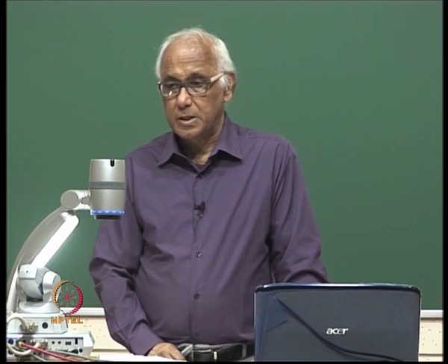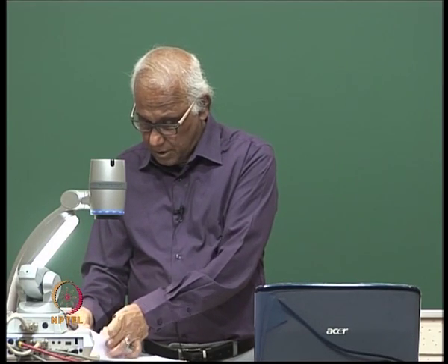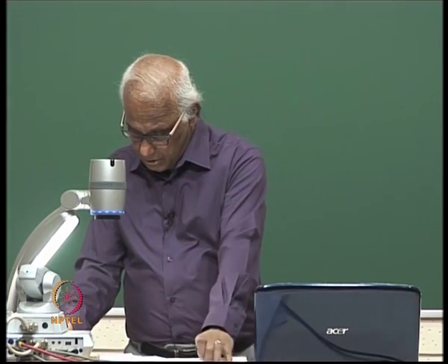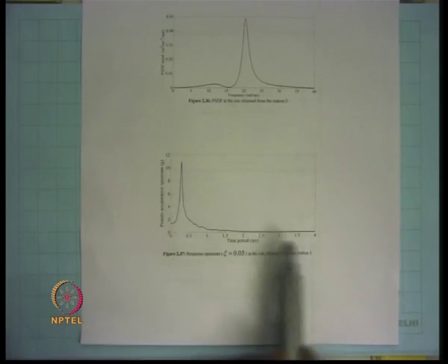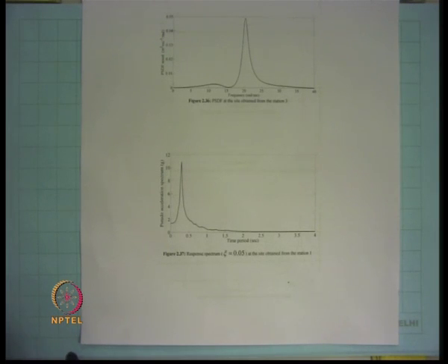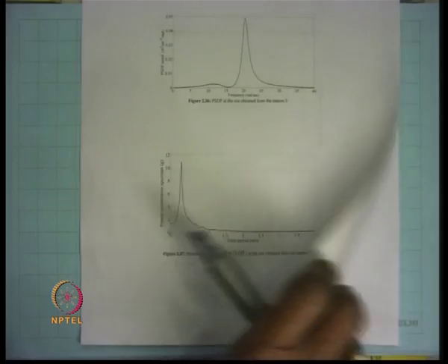From these 3 time histories of ground motion, we obtain the response spectrum, 3 response spectrums, and these 3 response spectrums are averaged and smoothened in order to obtain the final response spectrum, which is the site specific spectrum, and which is shown here in the last figure. So, this last figure shows the site specific spectrum, which is an averaged and smooth spectrum coming from the 3 earthquake records that have been synthetically generated.